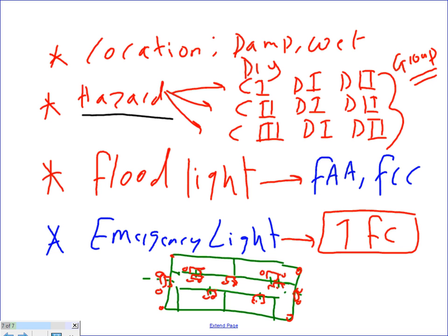These are three major classifications. Division 1, the hazard exists all the time. Division 2, under abnormal condition, the hazard exists. This is where we store this material. If there's an explosion, these are places where the lighting fixture could create an explosion. They also go by gas. What type of gas? For these two at least, they have groups. Not enough to say it's a flammable gas, but what group? Based on the group, the flash point of this gas would be higher or lower. The lower the flash point of the gas, the more dangerous the gas is, or the liquid or the vapor is.